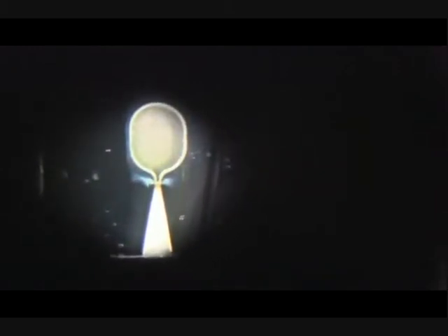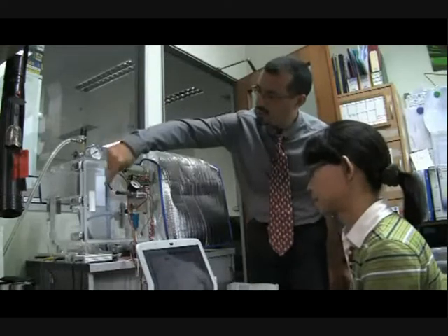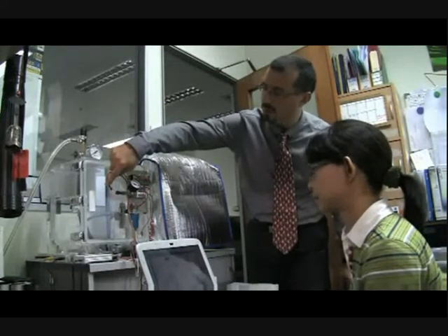So when we create these forces by means of small pulses of gas, then the force will rotate the satellite, and we can create our own design rules that will lead to optimal shapes of the micro nozzle, which means the optimal use of the propellant in the satellite.